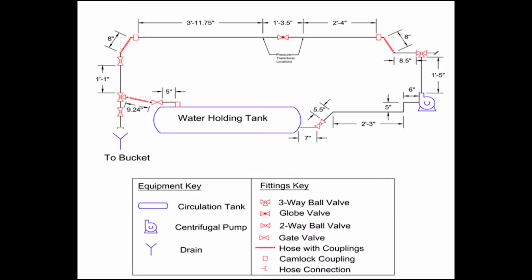Next, for the design problem, we want to estimate the pump's power consumption. To do this, we must obtain all the information for our particular system, including the pipe lengths and fitting types. We want to use this information to calculate the total friction loss over the system to then solve for the total pressure drop. Then, the power consumption of the pump can be solved using the total friction loss, which was determined in the last step.